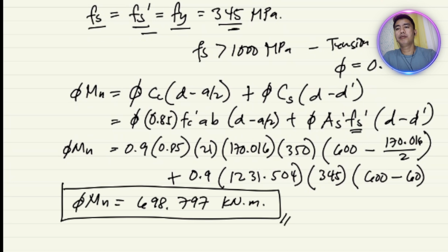Then, kung wrong, mag-assume naman tayo ng still does not yield. Okay? And then, check again. So, ngayon, yun nga, iterative yung calculation ng doubly reinforced. So, we need to assume and then check again. And then, dalawang assumption yan eh. The compression still and then the tension still. So, the first assumption is dalawa sila mag-yield.